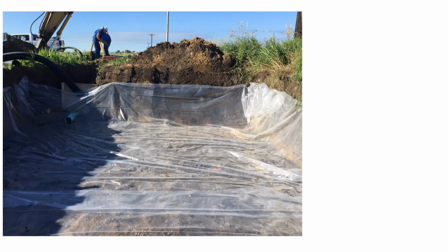You excavate out your pit. It's almost like making a big basement. You match the depth of that tile main generally on that bioreactor pit. You'll slope it a little bit just to get some grade in the pit. But for the most part, you match the depth of that main. You don't want to go deeper than the main because you want all the water to be able to get out of that bioreactor on that lower end. So wherever your outlet elevation is, you don't want to be below that outlet elevation on the floor of your bioreactor.